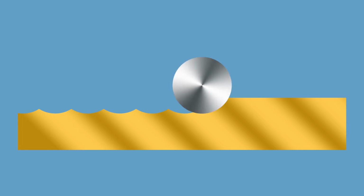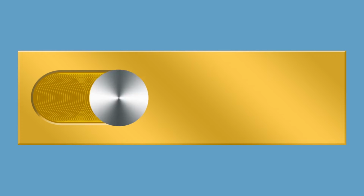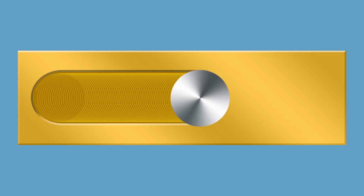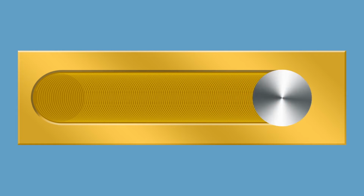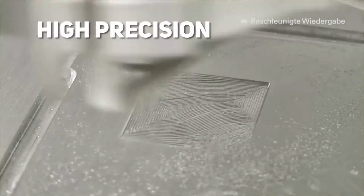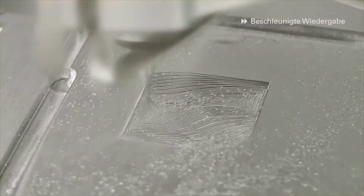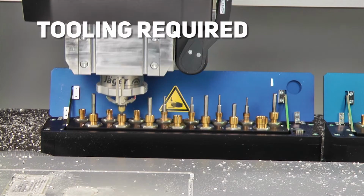A surface cut by the side of the cutter will contain revolution ridges, while face milling will produce trochoidal or revolution marks. Revolution marks are typically very smooth, and precise milling operations are capable of producing revolution marks that are only microscopic scratches due to imperfections in the cutting edge. An advantage of milling is that it is capable of much lower tolerances than punching. However, if existing milling cutters do not meet your job requirements, you will have to invest in custom tooling.